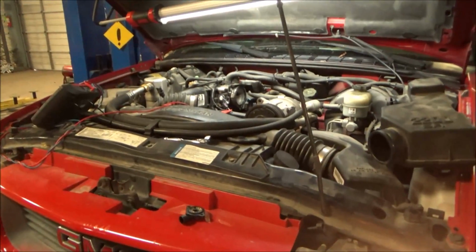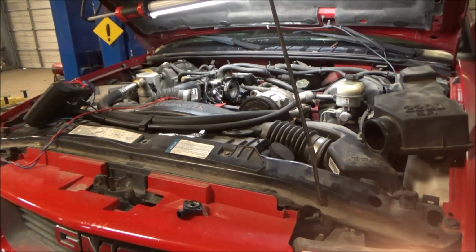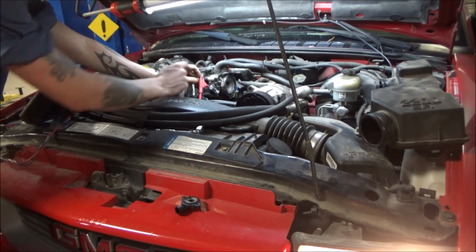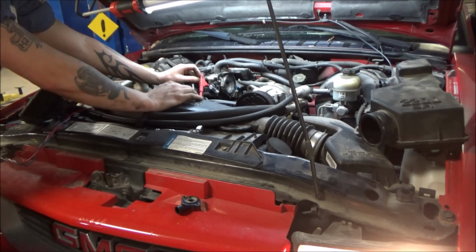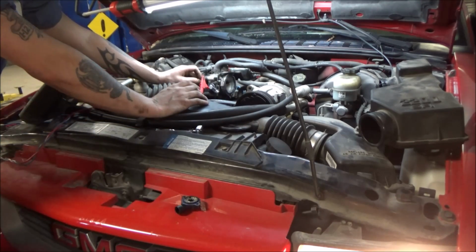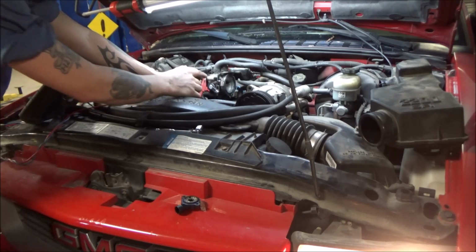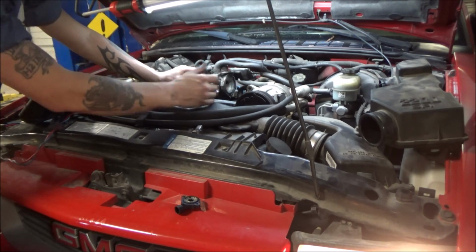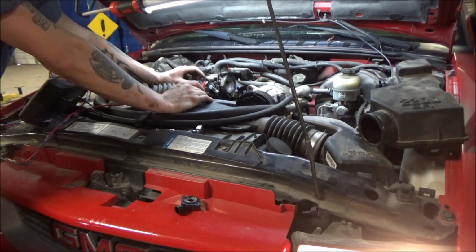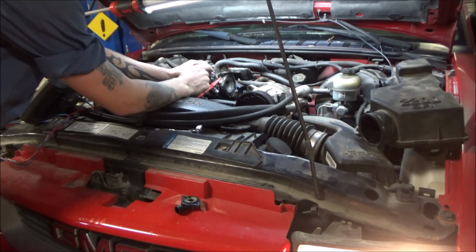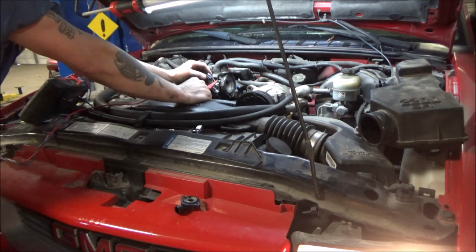So if we get focused back over here on the vehicle, in order to do this test, guys, we basically just need to pump voltage into the signal wire, which is the one that we're currently back probed in. We were looking at this number on the scan tool. It's currently reporting 0 volts. Basically, we just need to push voltage into this wire. There's a couple ways we can do that. I've seen some guys use 5,000 ohm resistors, and they just jump this signal wire to the reference wire. That's one way to do it.